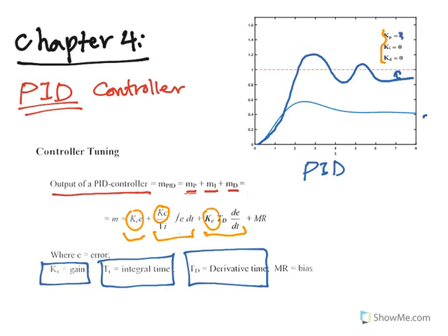In case we make this one 3, in case we have changed the I, for example, to 5, then we will have higher overshoot, more oscillation, and it will take a long time to reach the steady state or to come closer, and it will eliminate the offset, as you know.